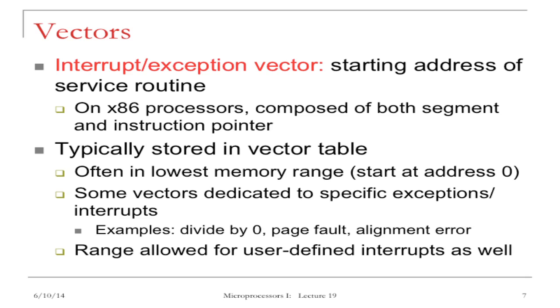Vectors, or more specifically, interrupt exception vectors. These are the starting address of a service routine. On x86 microprocessor, it is composed of both segment and instruction pointer, or CS colon IP. That's how we typically refer to a point in the program segment. And these vectors are typically stored in a vector table.